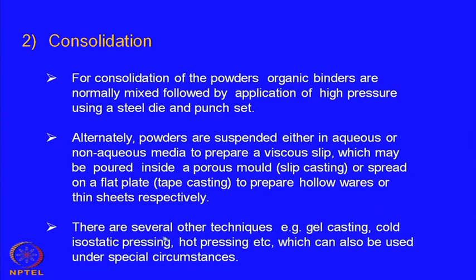Finally, there are several other techniques, for example gel casting, cold isostatic pressing, hot pressing, etc., which can be used under special circumstances. Gel casting is a technique very similar to slip casting, but the compositions are different; it is a suspension of fine ceramic powders in a material of gel consistency.